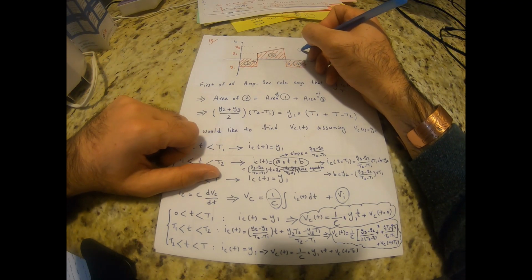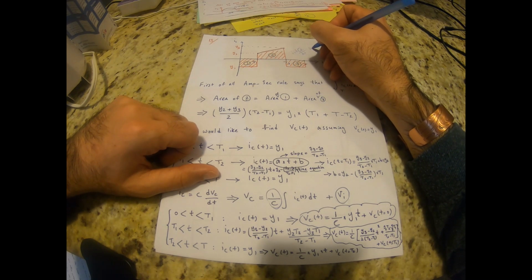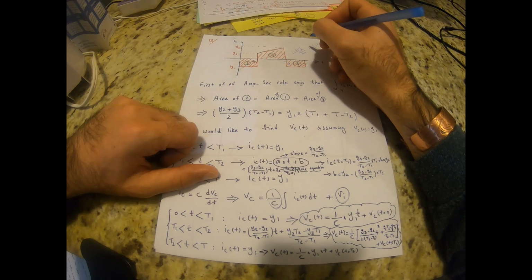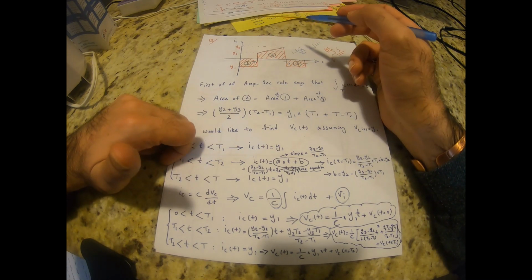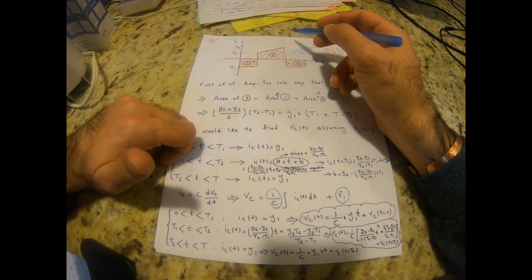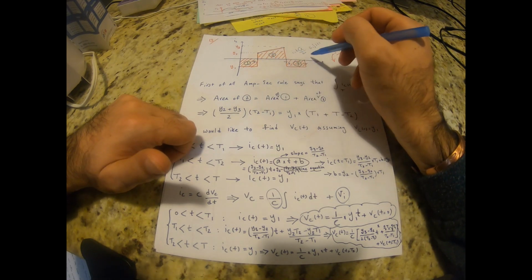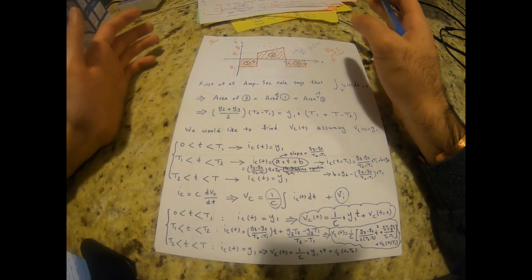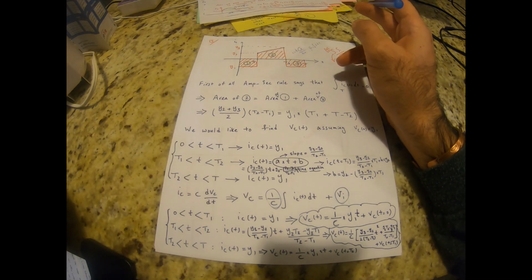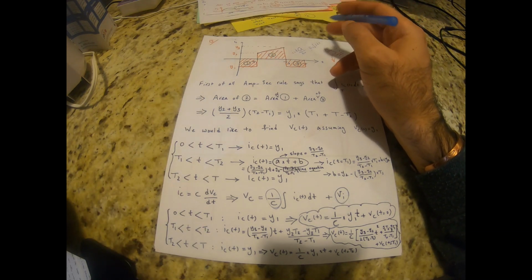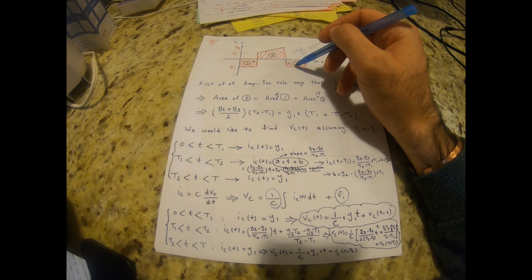If you remember, I is equal to dq over dt, so Q is equal to the integral of I dt. So this area actually represents charge. And amp-second balance tells us that the charge that goes inside a capacitor is going to be the charge that gets released from the capacitor if we are in an AC steady state. One other way of explaining this is the energy concept. It means the same amount of energy that goes inside the capacitor is going to go out of it.